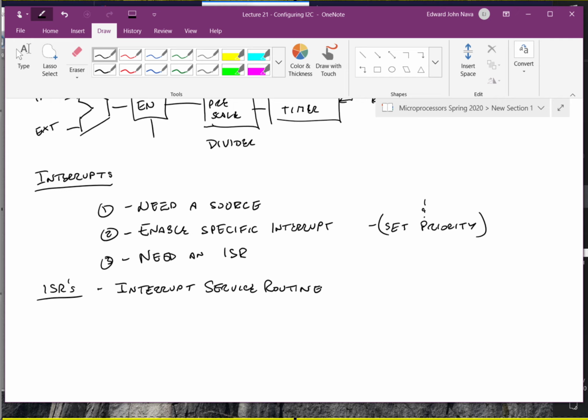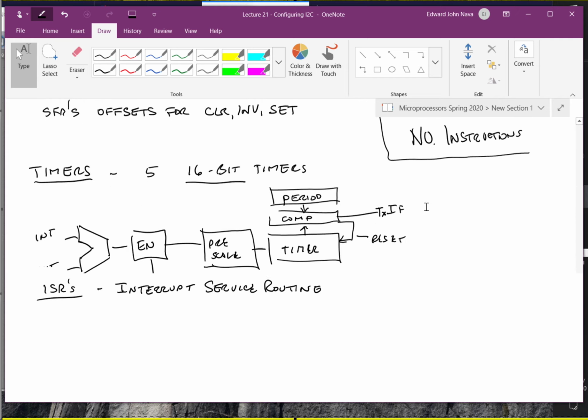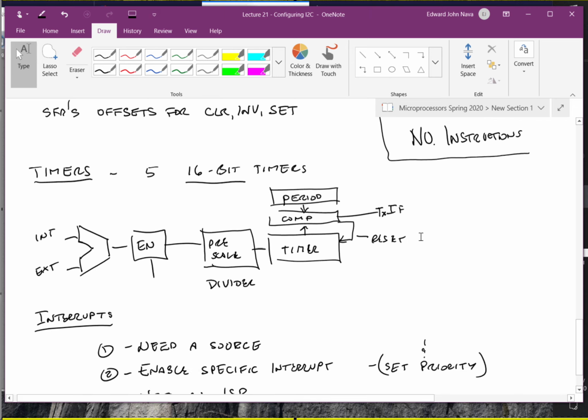So for example, if the timer generates an interrupt every 64th of a second, when that interrupt occurs, I might want to read sensors, do some sort of processing, and then resume some background task. And so that's, in my experience doing navigation systems, you have to periodically read accelerometers and gyros, and you call it a heartbeat.